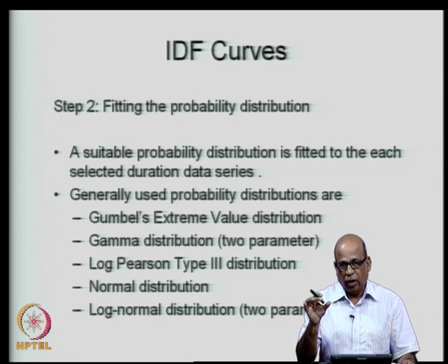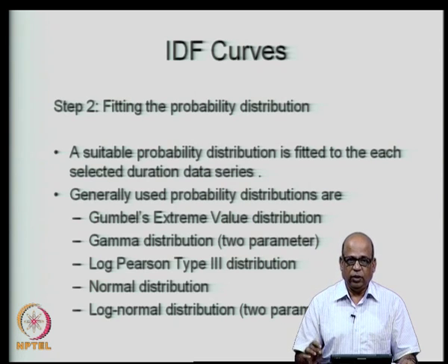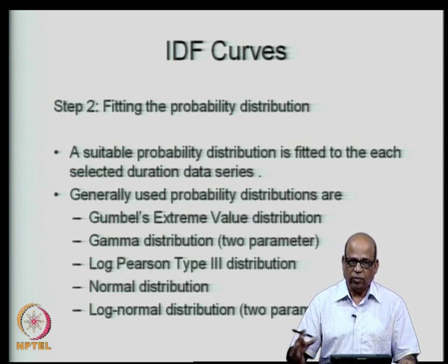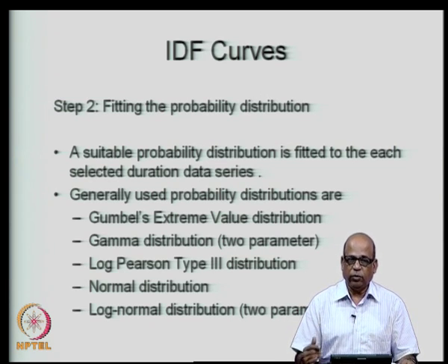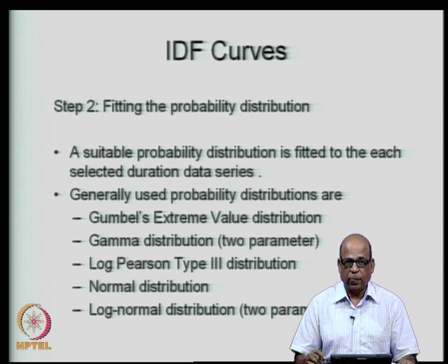So, you have constructed 1 hour data series, 2 hours data series, 6 hour data series and so on. Corresponding to each of these series, now we fit a distribution. What do we mean by fitting a distribution? We calculate the parameters of that particular distribution. And then we have to satisfy ourselves that the distribution that we are using in fact is a good fit for the data that we have.